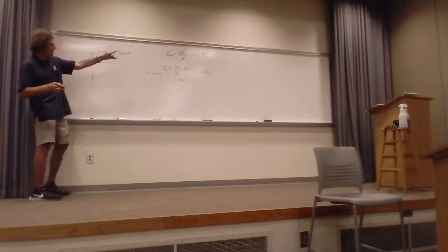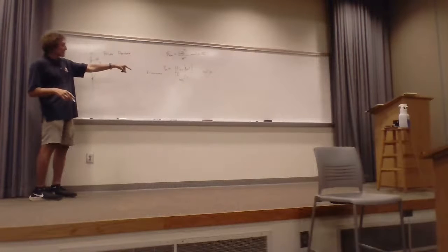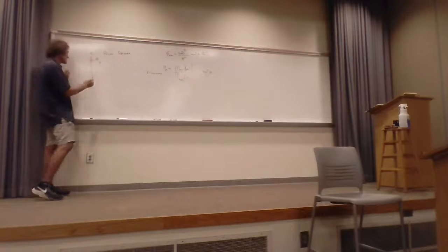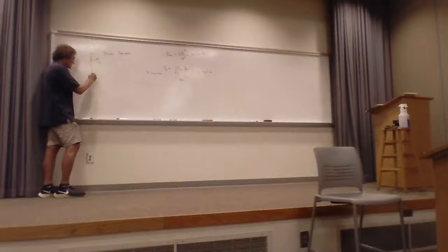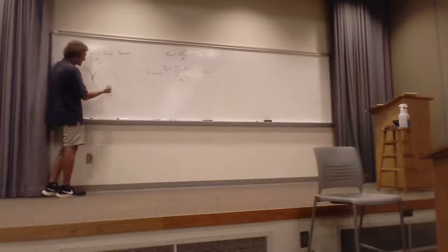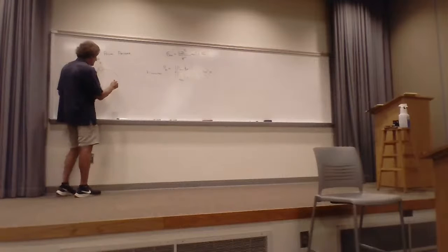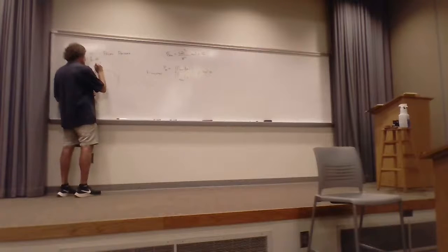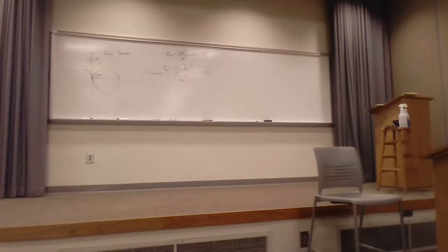So for that, by the way, that pattern right there, that's for a short dipole. I'm giving it away, but if I plot sine squared theta, start at 0 when you're going straight up, the length of the line would be 0, right? Sine is 0, 0. Well, as I go out, the line gets longer and longer, and I get this. Basically, I'm going to get a shape that revolves around the axis because it's not a function of phi. And the maximum value will be when this angle theta is 90 degrees. Y'all with me? So that's the radiation power pattern normalized.